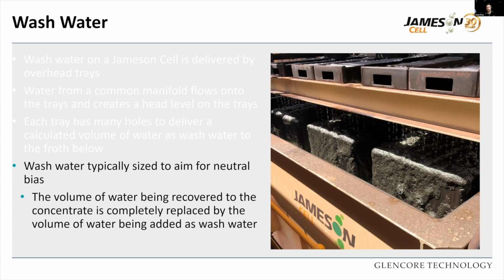It does depend a little bit on the duty and the commodity how much wash water is required. Particularly if it's a very fine grained material, possibly with a high feed percent solids, there may even be some benefits in going slightly higher than a 1-to-1 ratio. And there are other scenarios where you need hardly any wash water at all, if it's maybe a coarse feed and you're less susceptible to getting those entrained particles.